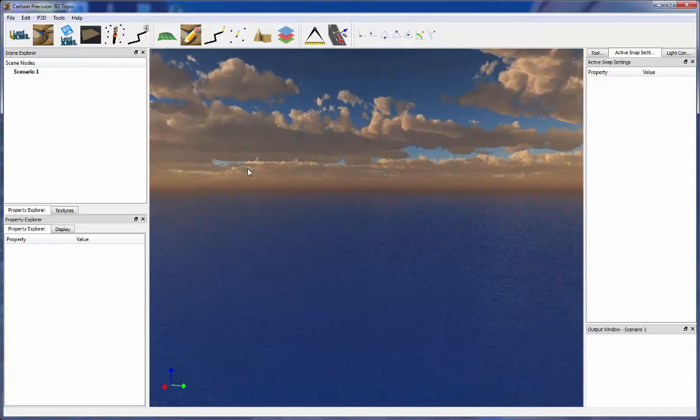This is an initial release for this product, and it is a 3D design environment that supports importing of data from Land XML files, Carlson TIN grid, and also DXF files. We can also import survey data from Carlson CRD files, Carlson PLN polyline files, and CL centerline files. And we also have a field to finish feature.